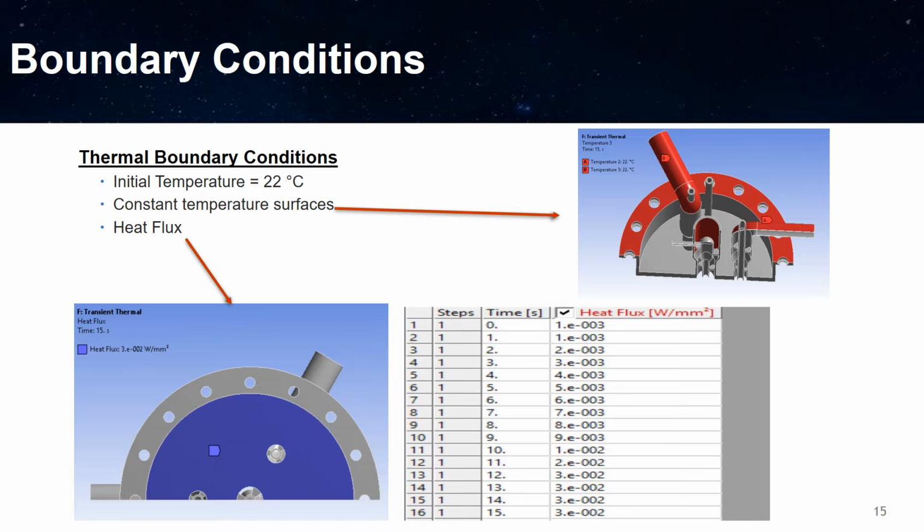Also the flange, because it's a 15-second test, the heat conduction through the bulk of the combustor to the flange is not that fast for the flange to see that amount of heat. And due to the purges going on around the injector, the temperature does not increase on the flange.